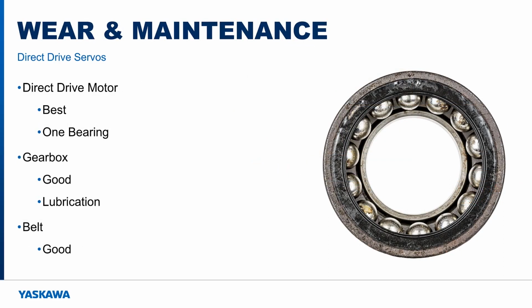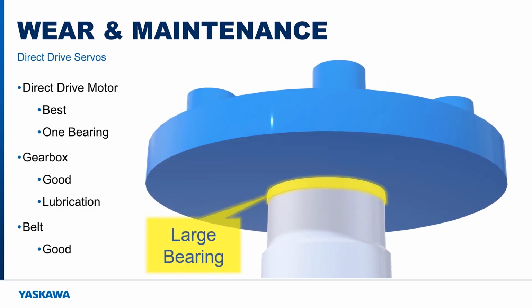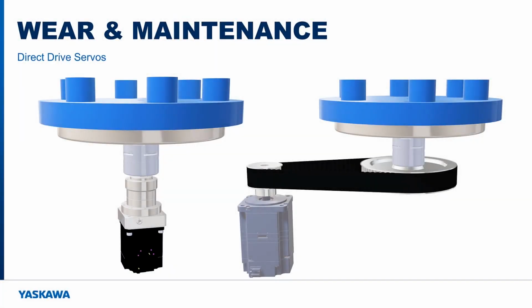A natural part of machine ownership is wear and maintenance. In a direct drive motor, the main motor bearing is the only point of friction and wear, and these motor bearings are typically sized for extremely heavy loads. But gearboxes and belt transmissions have other moving parts that wear out, may require lubrication, or other periodic maintenance. Audible noise is also louder compared to direct drive motors. As they wear, the performance of these transmission-based mechanisms begins to decline. The backlash and stiffness get a little worse every day. Therefore, expect position settling time, accuracy, and repeatability to continually degrade as time goes on.